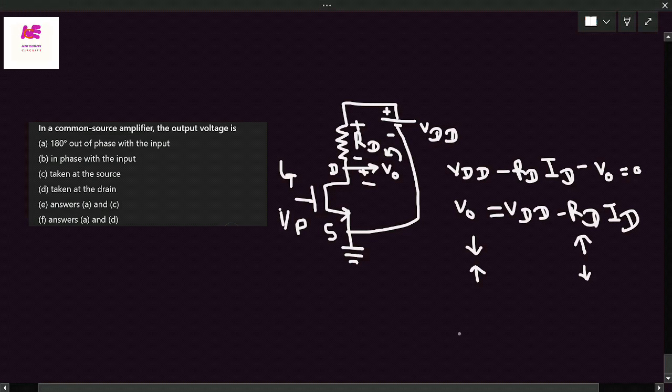Now, we are moving towards the small signal analysis. Why is small signal AC analysis performed in an amplifier? The main function of the amplifier is to increase the strength of the signal. So in order to get the amplified version of the input at the output, we need to apply a small AC signal, and we have to consider some internal parameters to calculate important parameters like gain and bandwidth. These are two important parameters in the amplifier, and that is the reason we are considering the small signal analysis.